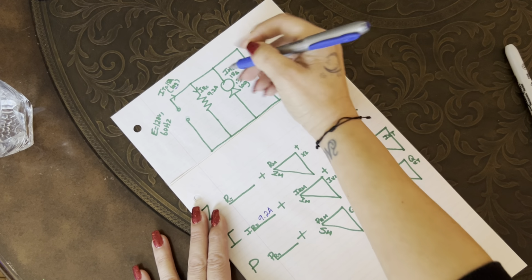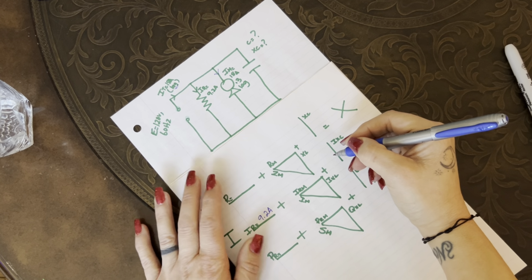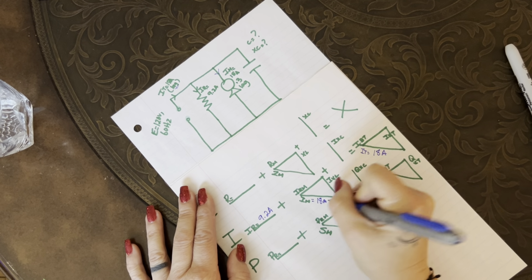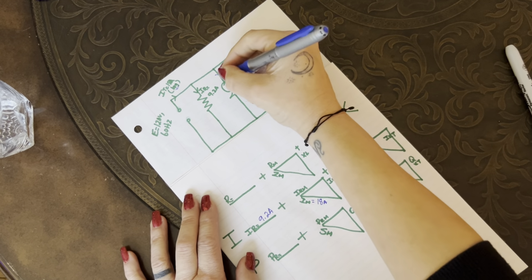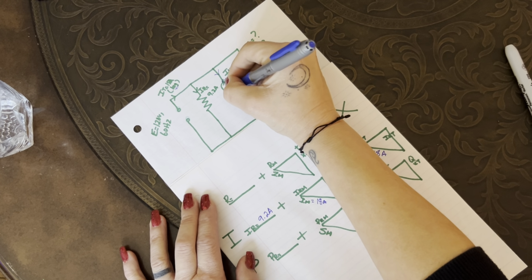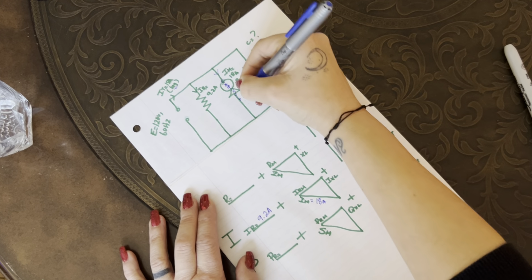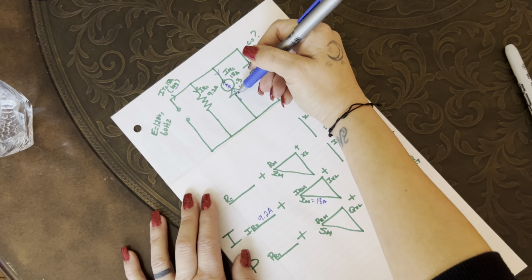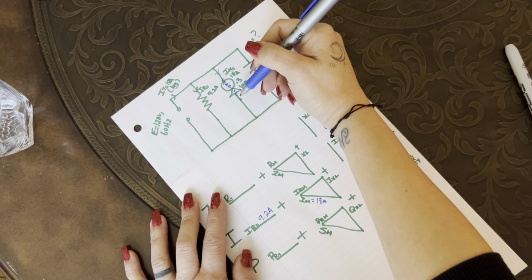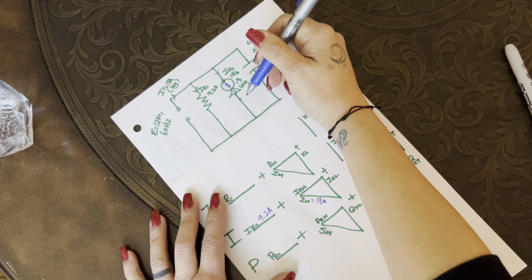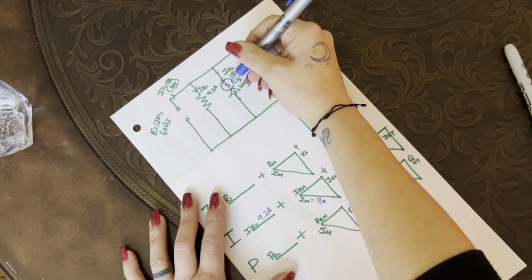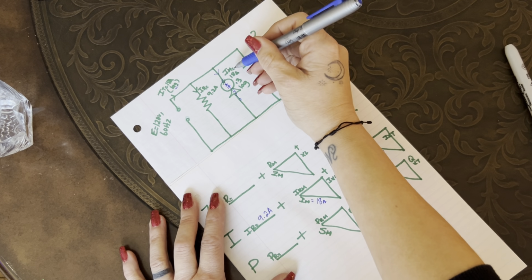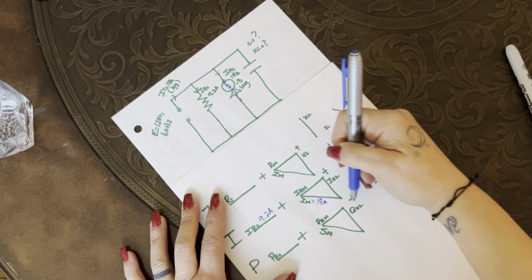Then the motor current. They're telling me the current that's flowing through that motor is 18 amps. So it's important that you're putting that on the hypotenuse of your motor current triangle because essentially your motor is just a series circuit contained with 120 volts across it. The resistive portion is 90 degrees out of phase with the inductive portion, so I cannot just take those currents and vectorially add them together. They're out of phase with each other. I don't know how much voltage is across the resistive portion. I don't know how much voltage is across the inductive portion. So whenever they give you the incoming current for the motor branch, that is always going to be the hypotenuse.